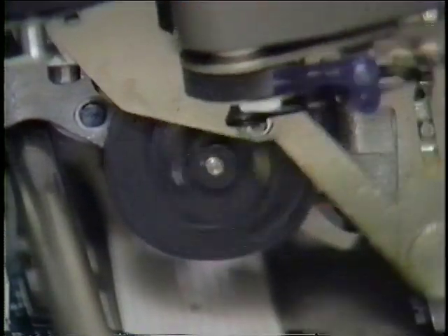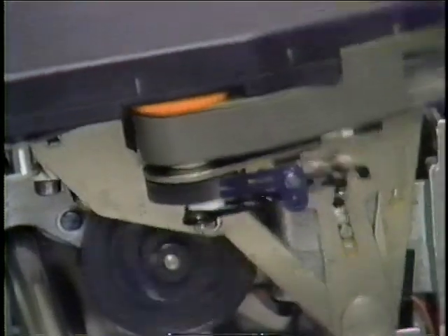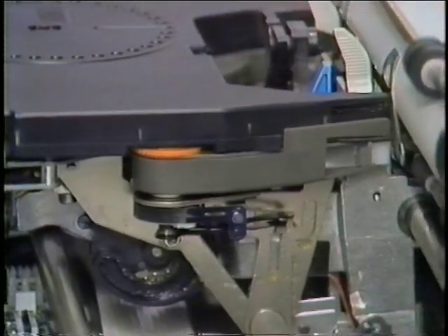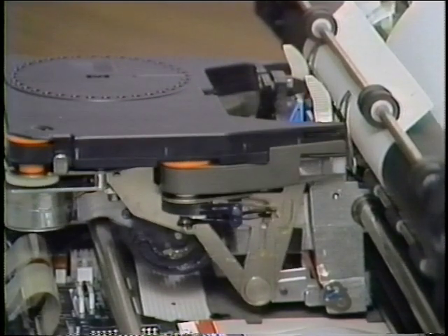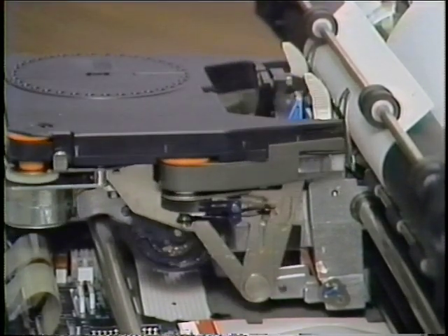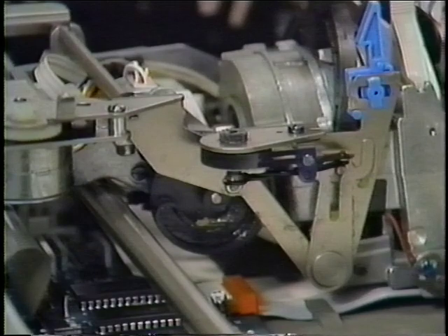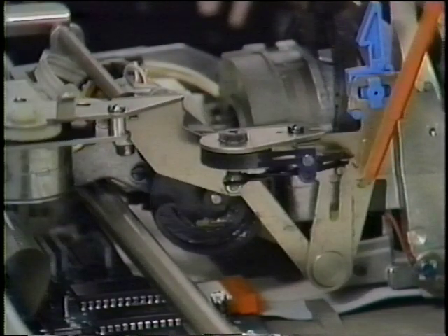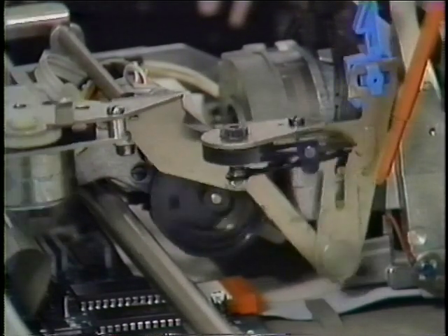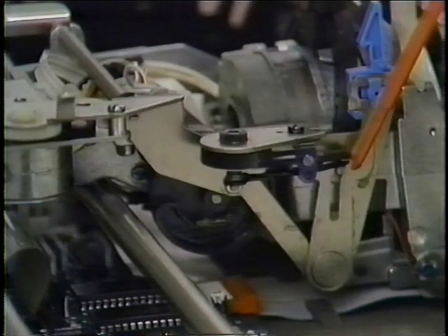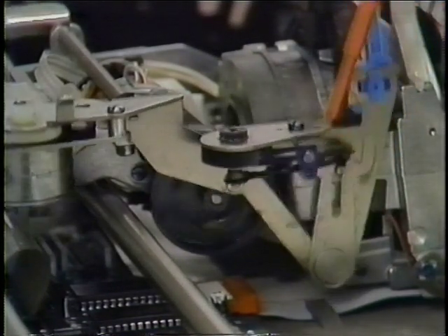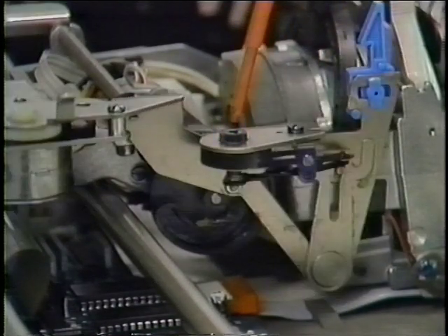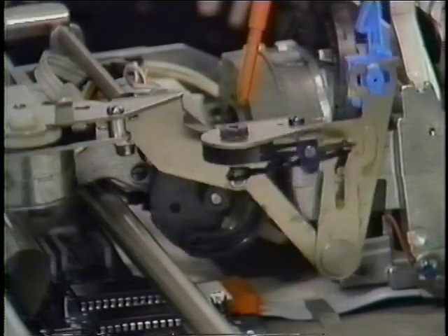Pressing the correction key button causes the ribbon lift motor to drive the ribbon lift cam until the ribbon plate is high enough so that the correction tape is in front of the character pedals. The correction tape feeds as the ribbon plate is rising. When the camming surface in the correction feed arm moves against the correction feed cam follower, it provides motion to the correction feed ratchet through the drive link.